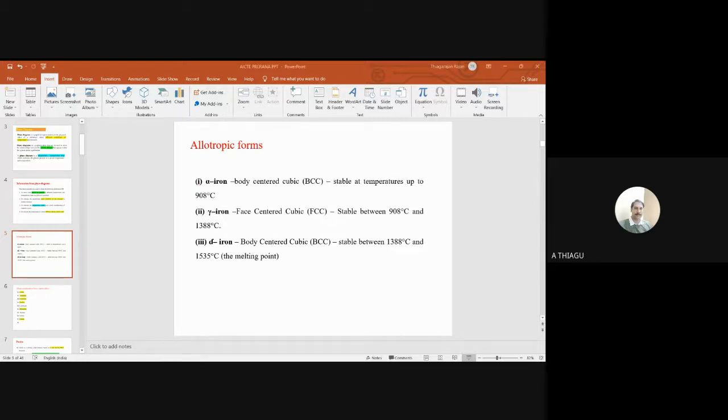classification of cast iron. We are all aware that cast iron has a high percentage of carbon. Once you hear the term cast iron, it means a hard and brittle material. You can give many examples: pump casings, couplings, and engine cylinders are made from cast iron. It has high hardness and high temperature resistance, but the drawback is its brittle nature.